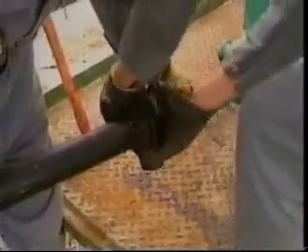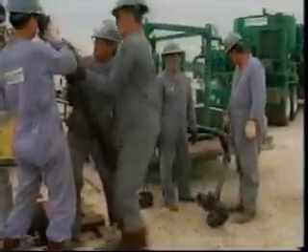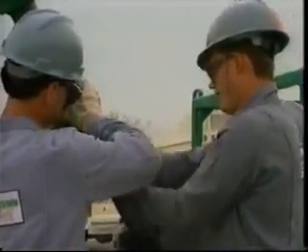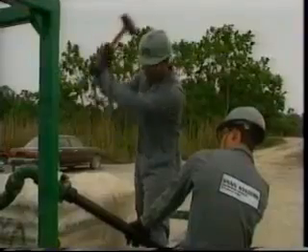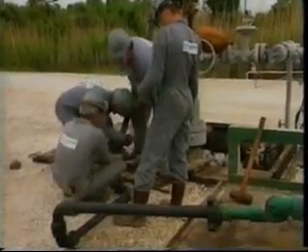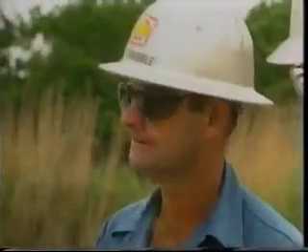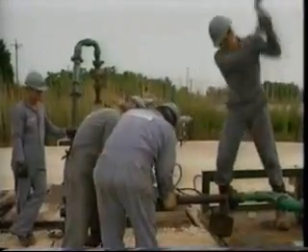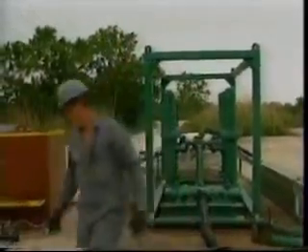Based on reservoir permeability, composition, and results of previous acid treatments on nearby wells, a 12% HCl, 3% HF acid has been chosen. A pre-flush with 15% HCl and an after-flush with 3% ammonium chloride will also be used. Because this reservoir is partially depleted, the fracture gradient has changed from the initial fracture gradient of 0.6 psi per foot. The current fracture gradient, and then the maximum treating pressure, can be determined in several ways.